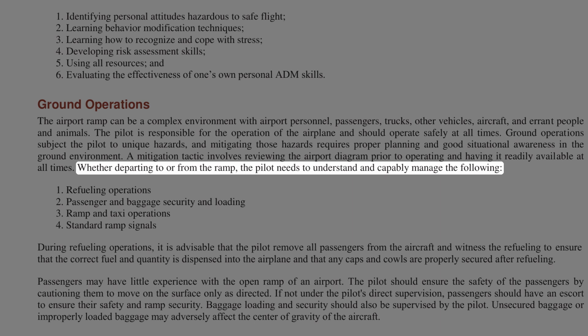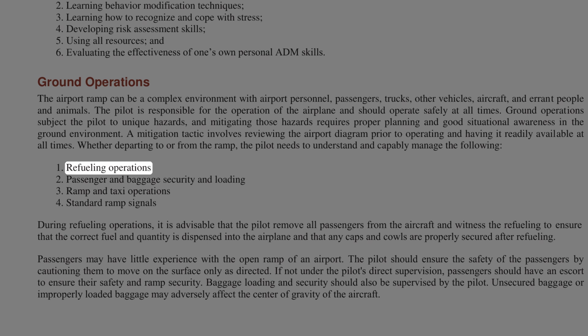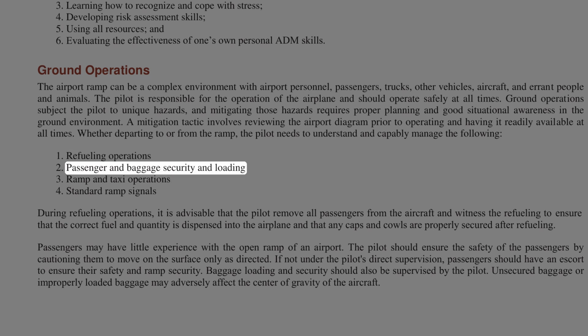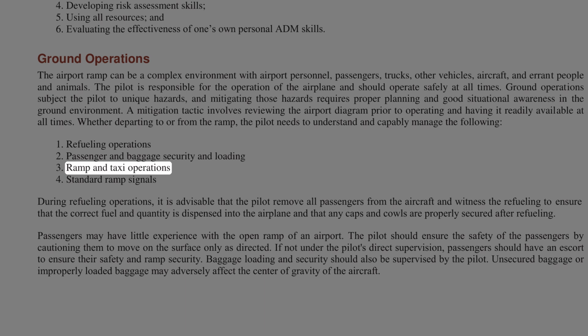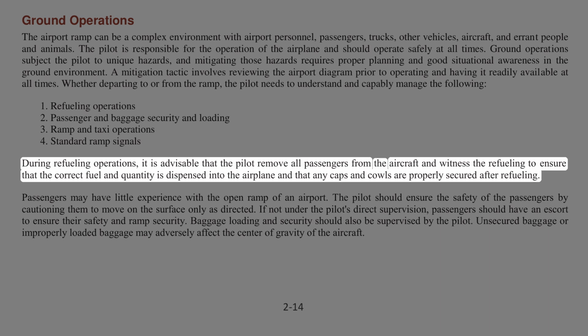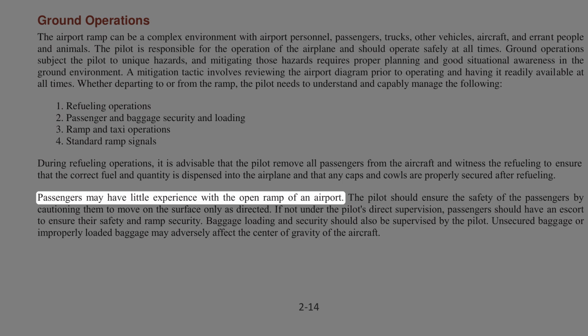Whether departing to or from the ramp, the pilot needs to understand and capably manage the following: refueling operations, passenger and baggage security and loading, ramp and taxi operations, standard ramp signals. During refueling operations, it is advisable that the pilot remove all passengers from the aircraft and witness the refueling to ensure that the correct fuel and quantity is dispensed into the airplane and that any caps and cowls are properly secured after refueling.